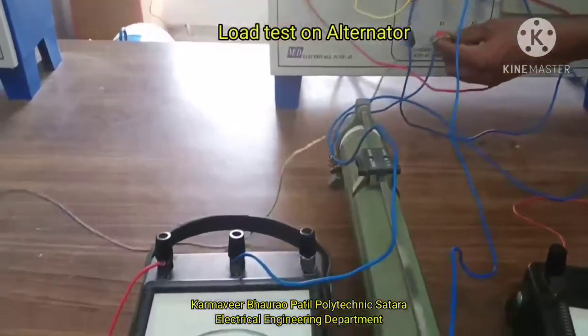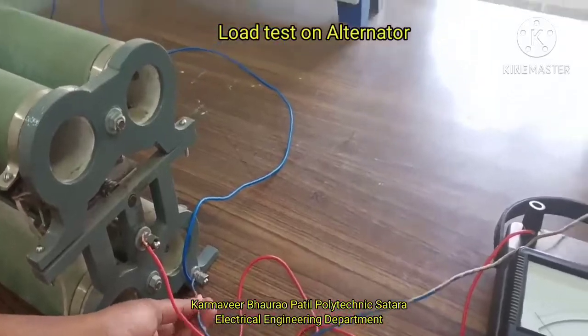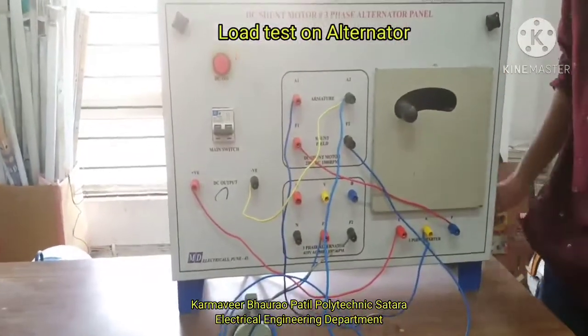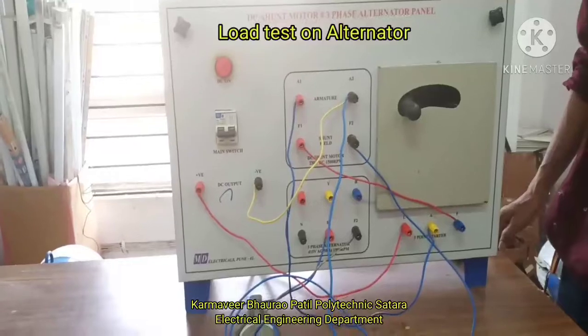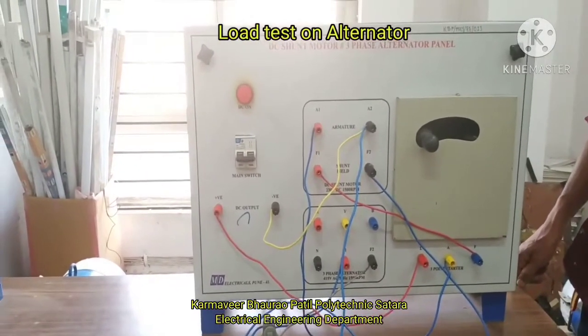F2 will be again connected to negative of the rheostat. So that completes the connections for the field winding. Now this much connection we already did in the last experiment. What connections we want to make now are the connections for the load.